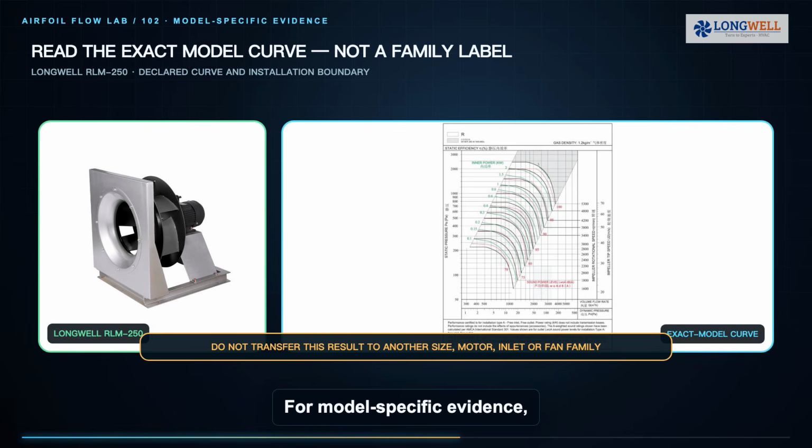For model-specific evidence, this Longwell RLM250 page plots pressure, efficiency, power, speed, tip speed, and sound power information for its declared test and installation conditions. Mark the required duty point on the exact model curve. Do not transfer an RLM250 result to another diameter, motor, inlet, or fan family.